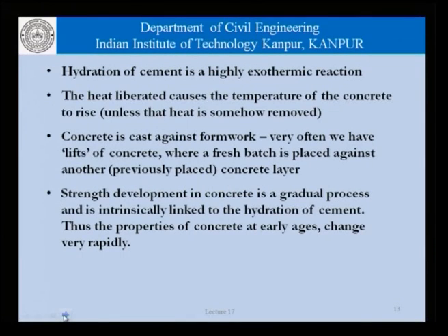This is a summary of the fundamentals that we studied last time. Hydration of cement is a highly exothermic reaction. The heat liberated causes the temperature of the concrete to rise unless we are able to remove the heat from the body of concrete very quickly. We should remember that concrete is cast against formwork, and very often we have lifts of concrete where a fresh batch is placed against another one, which could be a previously placed layer of concrete or against rock or ground or whatever it is.